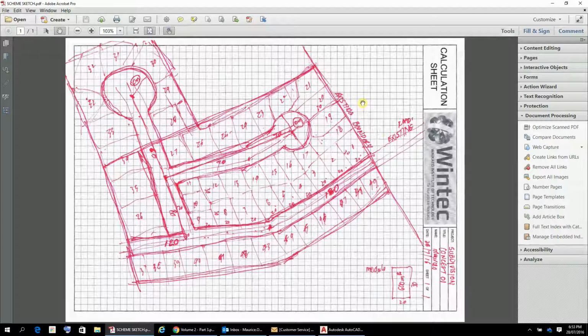I'll have to come up with some surfaces for the existing road, and existing sewer and stormwater and water connections will possibly all be in here. What would be the most advantageous surface? I'm suggesting a surface gently rising up through here, possibly 4 metres, and again rising in this direction, which would enable all facilities and reticulation to generally flow down to this direction here, which will provide stormwater, water and sanitary sewer outlets.